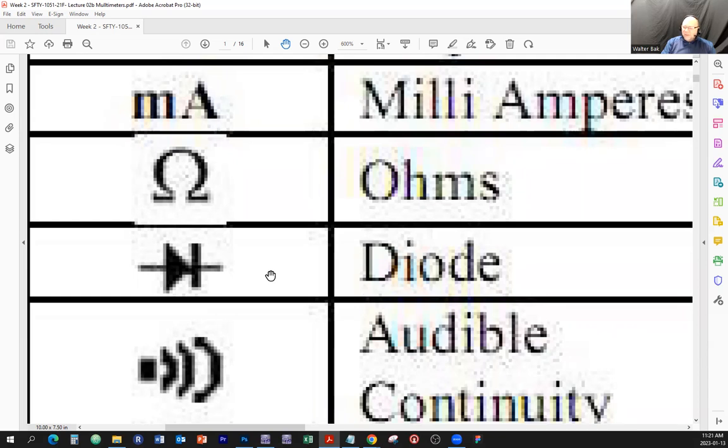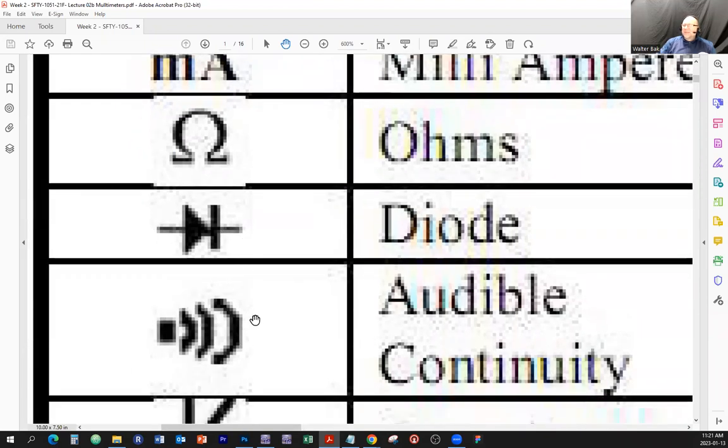If you really want to find out what this forward bias voltage is, then you need to connect a circuit. Connect the LED diode in series with the current limiting resistor. So you could have something like 330 ohms and 5 volts, or maybe 6 volts or 9 volts. Connect the diode and make a closed loop, and then measure the voltage across the diode. And it should be something close to what the specifications are saying on the data sheets of the diode. Okay.